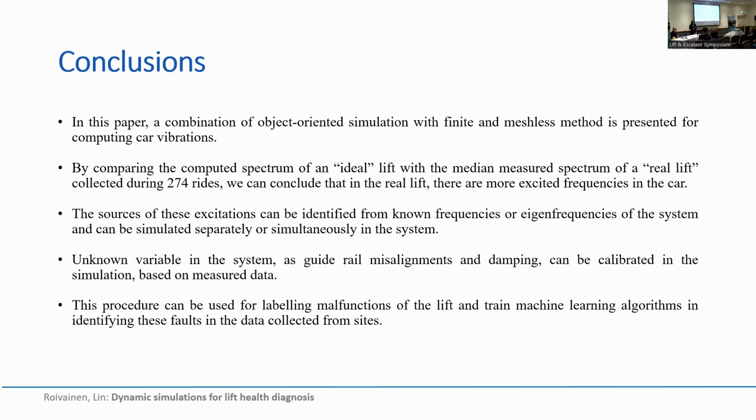Conclusions. In this paper, a combination of object-oriented simulation with finite and meshless methods is presented for computing car vibrations. By comparing the computed spectrum of an ideal lift with the median measured spectrum of a real lift collected during 274 rides, we can conclude that we don't have ideal lifts on the site.